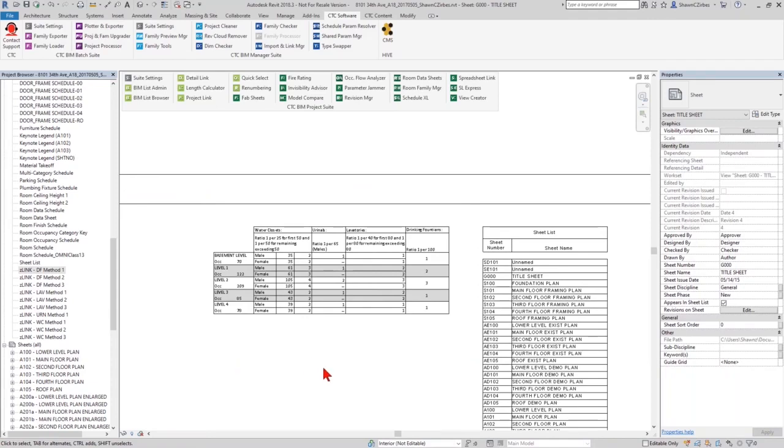And the next time there's design changes from the architecture team, I simply rerun Spreadsheet Link and apply my room properties back, and then just refresh my schedule Excel list, and I print, and I'm done. That's 5 minutes for full occupancy calcs, full code compliancy calcs on a real project, 5 minutes or less, and I'm ready to print. As opposed to the manual process of validating visually for 2 hours and then re-updating those links and then printing. This saves you 2 hours every time you want to print if you're doing calculations in this type of fashion. It can make it real easy.